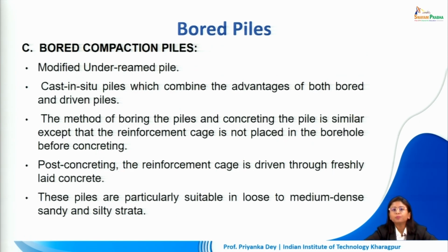Then comes the bored compaction pile, and it is a modified form of the underream pile. Now this cast in situ pile is actually a combination of bored and driven piles. So it has characteristics of both, and the construction process is also quite interestingly a combination of both.